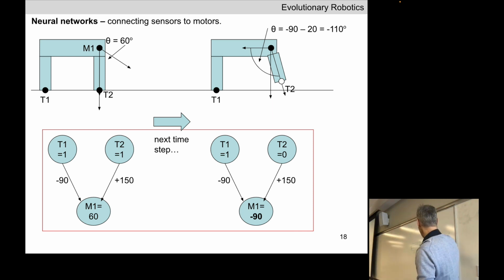Yeah? Let's say I attach link 1 to link 2 with another joint out here, 1_2. I want the whole snake to continue rotating horizontally through the plane. So link 1 and link 2, I also want them to rotate through the horizontal plane. I give this joint the same joint normal, right? So this would define a 3-segment snake that's rotating horizontally on the ground. You can try this if you want.